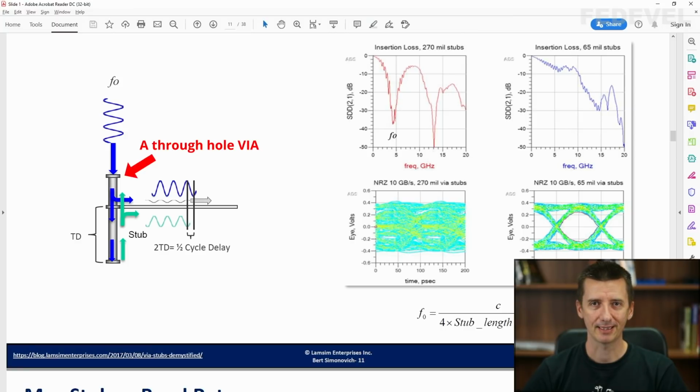If you are designing PCBs, then you probably read some articles on the internet which are talking about some small things which can influence the quality of the signals on your PCB. Small things like the unused part of a via, or via stub. Maybe you read that this can influence the quality of the signals in your PCBs.